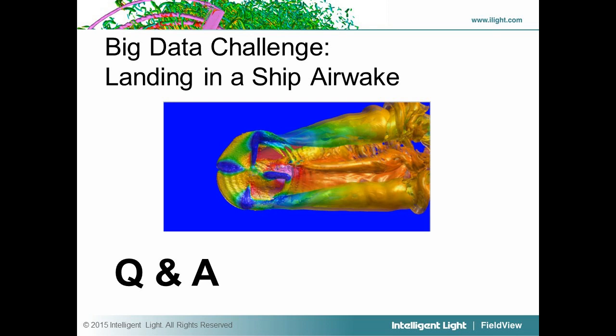And it also has engine models you can integrate. There's a number of engines that have been coded up as engine models. If you have a source sink boundary condition, instead of just crudely putting stuff in, you can actually put it in as engine inlet, engine outlet, and have the engine module calculate what happens in between and set the boundary conditions. And then you can control the power level angle for the engines.